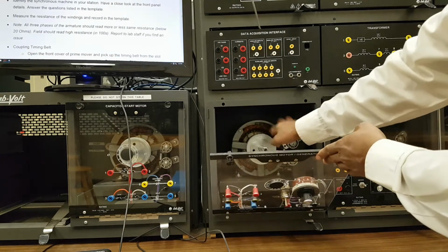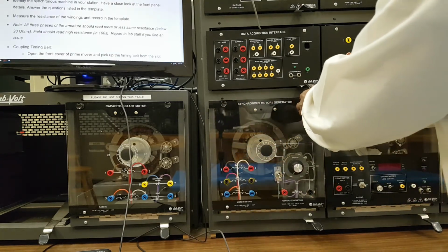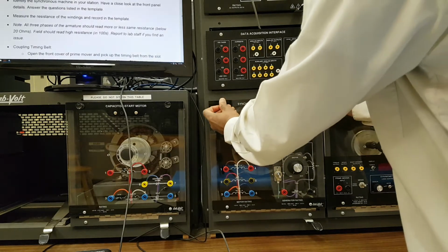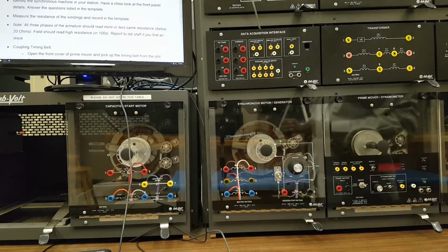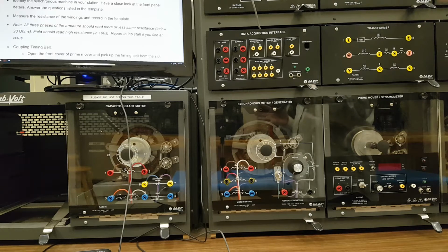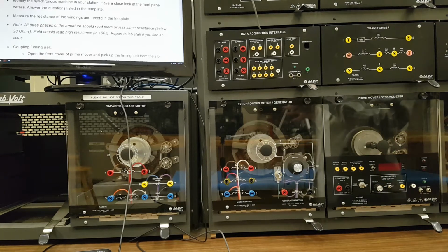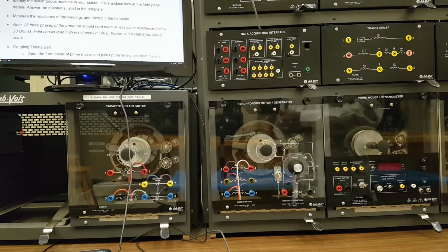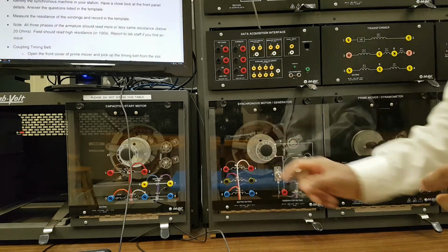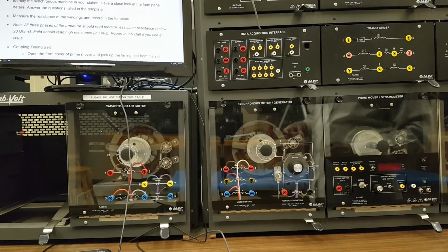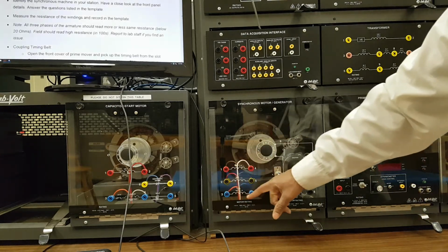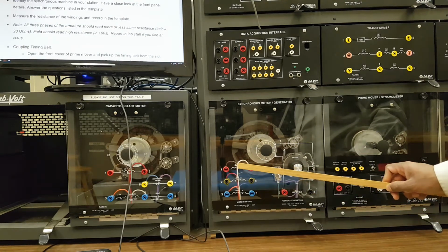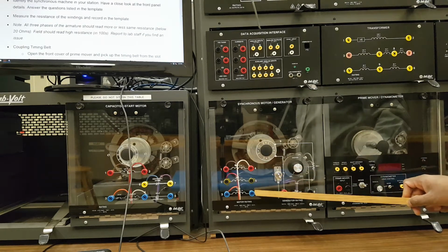and from there, as it's rotating, there is a winding, the armature winding, and also there's a field winding that provides the flux. If a flux is there and the armature conductor is rotated in the magnetic field, the resulting thing is the voltage will be available at the windings there. That is the basic idea of the synchronous generator. Quickly, these are the three armature windings here. So this is a three-phase machine, that's why we have three windings there.